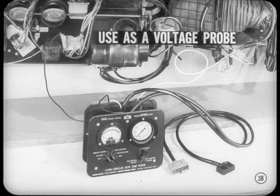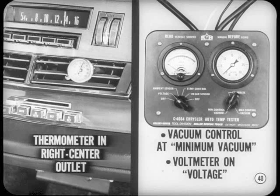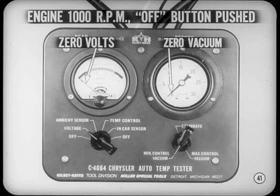the various operating conditions. The operating conditions are as many and as varied as there are combinations of signals from the two sensors and the instrument panel selector. It's almost impossible to predict every condition of temperature, so let's look at some basic possibilities. To prepare for the push-button test, place a thermometer in the right center air conditioning outlet. Set the vacuum control dial at minimum vacuum and the voltmeter dial on voltage. With the engine running at 1000 RPM and the off button pushed, the tester voltmeter and the vacuum gauge will read 0. This is the starting point to check out the operation of the entire system.